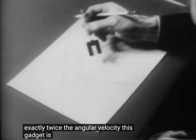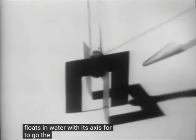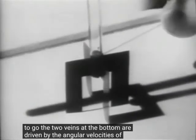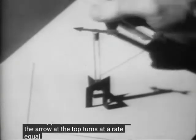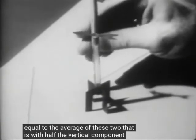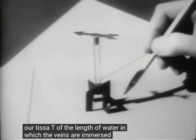It is exactly twice the angular velocity. This gadget is a vorticity meter, which floats in water with its axis vertical. The two vanes at the bottom are driven by the angular velocities of two mutually perpendicular fluid lines. So the arrow at the top turns at a rate equal to the average of these two. That is, with half the vertical component of vorticity of the lump of water in which the vanes are immersed.